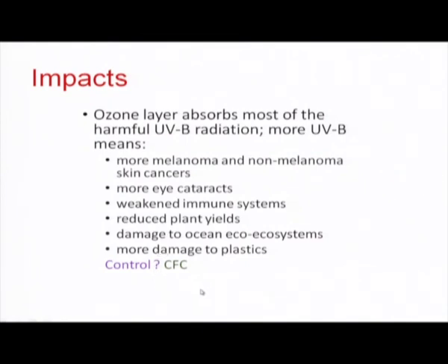So, the main precursor for this ozone layer depletion is CFC. This has to be controlled. As per the Montreal Protocol, almost all countries have agreed to stop using CFC for cooling related purposes. All domestic refrigerators available in the market now are CFC free. So, that way we have made a significant contribution in controlling emission of CFC compounds into the atmosphere. If we completely stop any chlorine containing compounds, we can definitely minimize these impacts, and we can protect the stratospheric ozone, where a steady concentration of about 10 ppm is present.